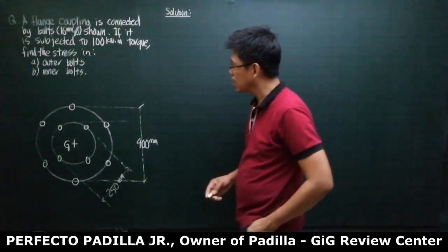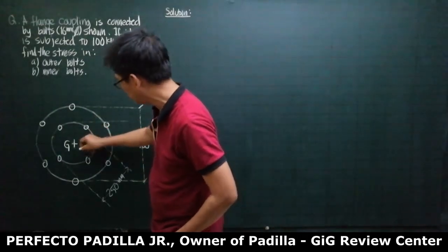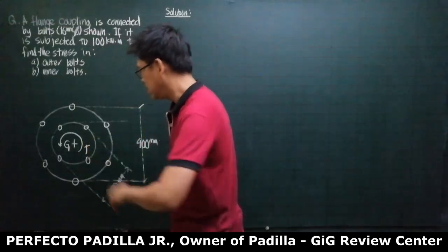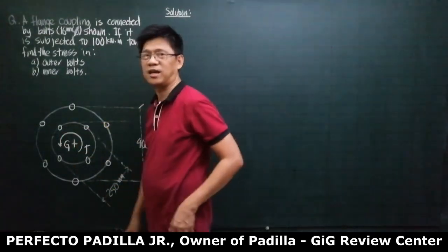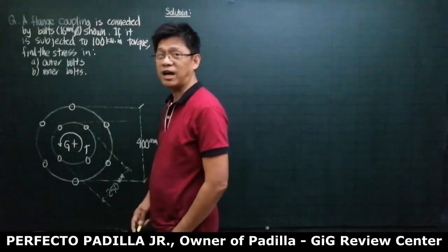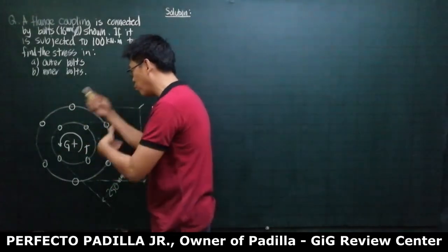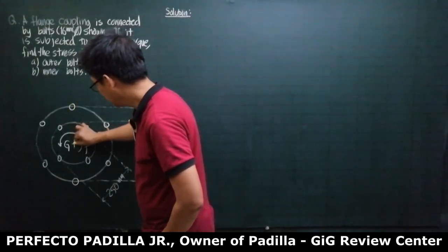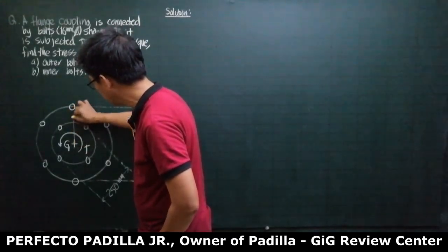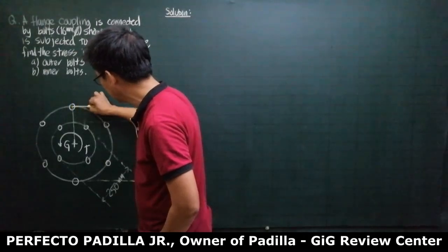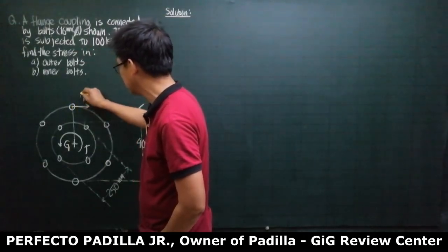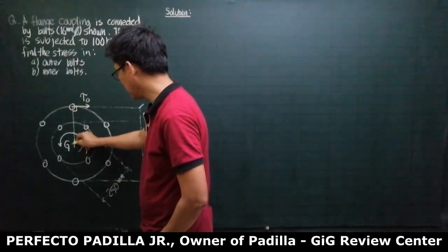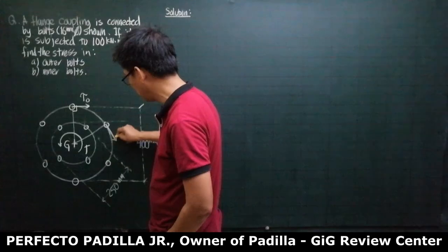If it is subjected to a torque of 100 kilonewton meter, so let us say that that torque is this one, this is T, this is counterclockwise, then each bolt will react to produce a clockwise moment about G. For example, the outer bolts. So its distance from the center is this. So it will produce this stress. So this is the stress in the outer bolts.